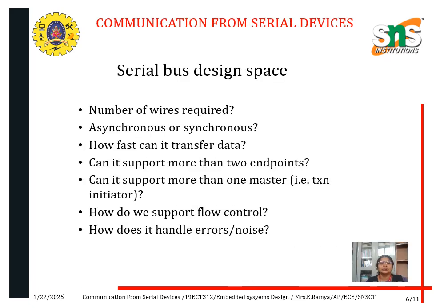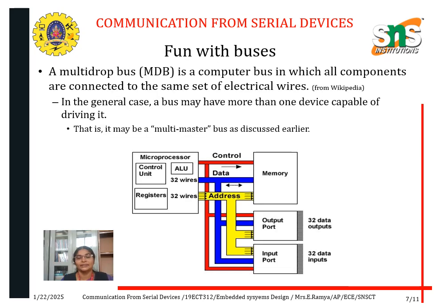Serial bus design space: number of wires required, asynchronous or synchronous, how fast it can transfer data, whether it can support more than two endpoints, whether it can support more than one master, how we support flow control, and how it handles errors and noise.